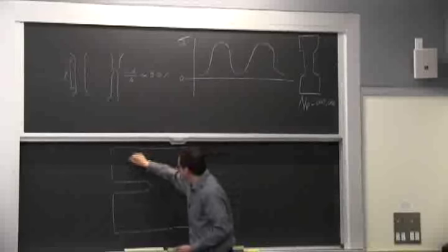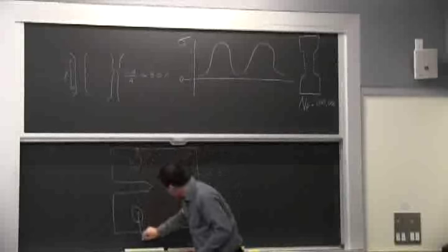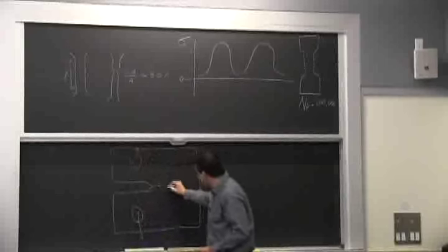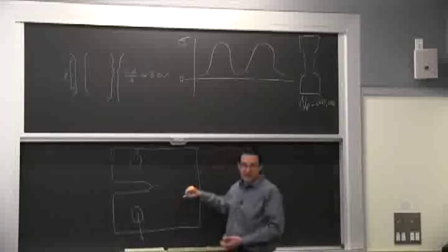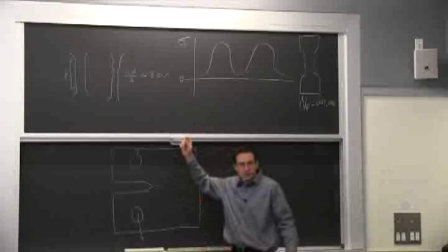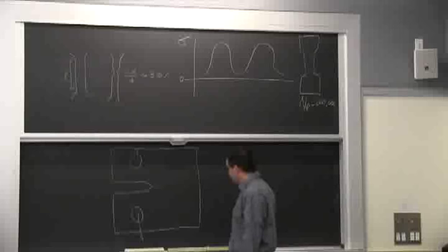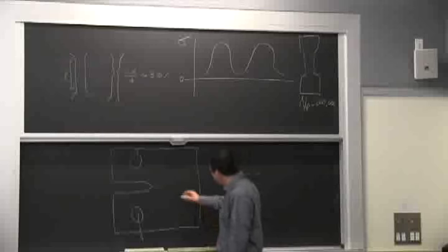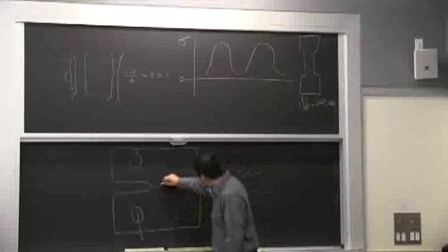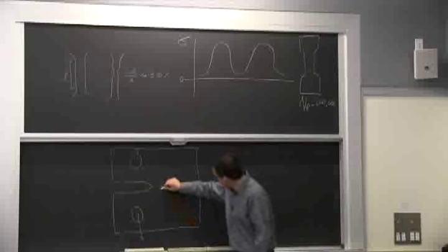So you've got the holes. You're going to load it here. You'll form a little pre-crack by fatigue, and then eventually you just open it up to get an overload. Now, if it's a plastic or a very ductile material, and it turns out your plastic zone becomes this big, just for an example, so that's my plastic zone here after the pre-crack when I try to do my K test.